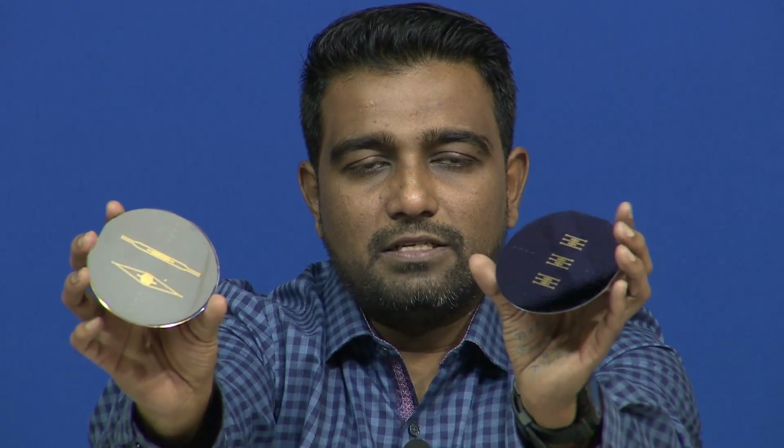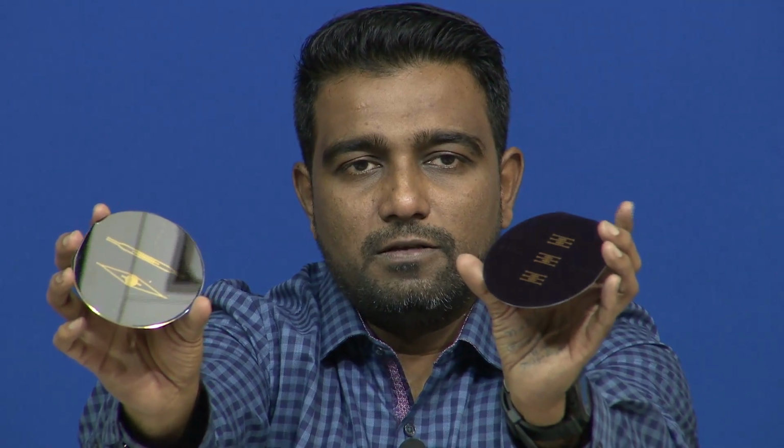Do not worry about the pattern, just worry about the color, silicon oxide on silicon, very easily you can identify, correct, back side is oxide of course. So, in here we have etched the oxide from the front side. In here there is oxide on the front side, oxide on the back side, oxide on the front side, oxide on the back side, alright. Here no oxide on front side, but there is oxide on the back side. Okay. So,